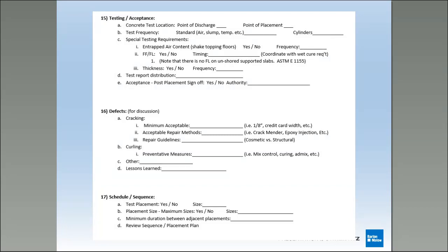And then, of course, always have a placement plan to follow. Your place and finish contractor should have all of his placements mapped out and planned in a sequence. As a polisher, you're going to want to see that plan and sequence, because if I'm polishing behind a place finish guy, I want to follow that so I can optimize my cut. I don't want to start where maybe it's not the longer cure time and I'm cutting real easy, so I'm using a certain set of diamonds and resins, and I work myself backward, not knowing his sequence, and I get to the longer cured slabs and I'm going to fight it all the way through. So you want to be in on that sequence he's got laid out for you and the durations of when you're going to be placing.